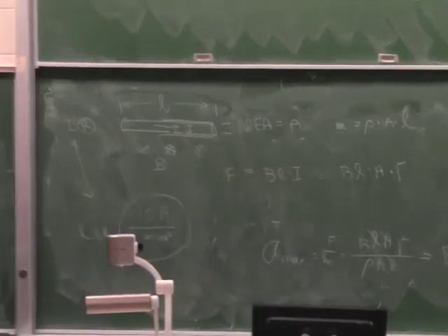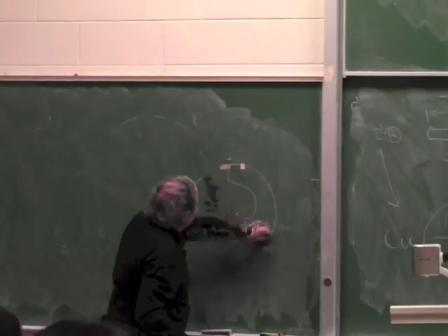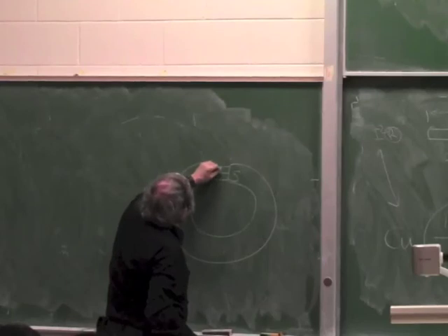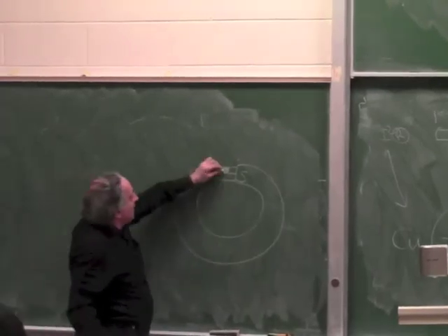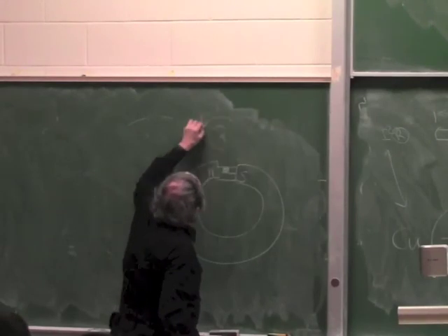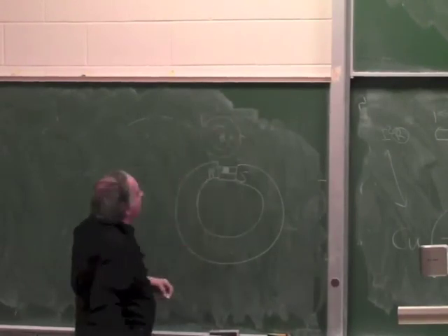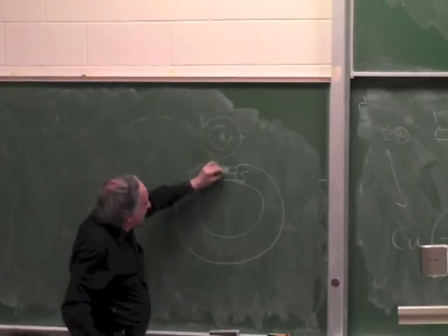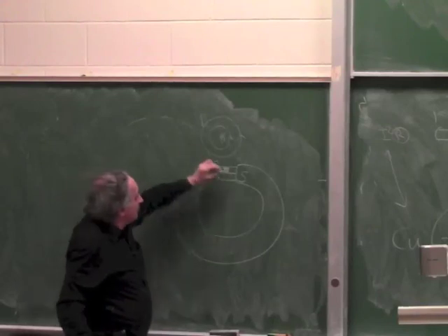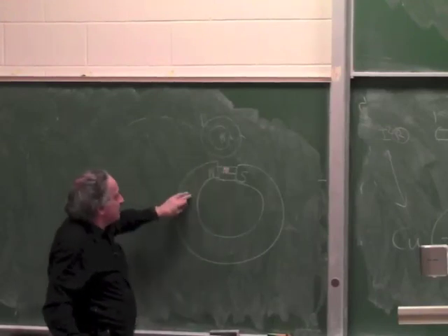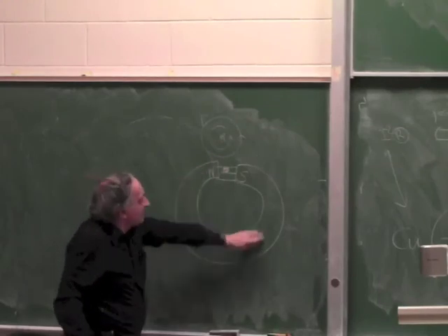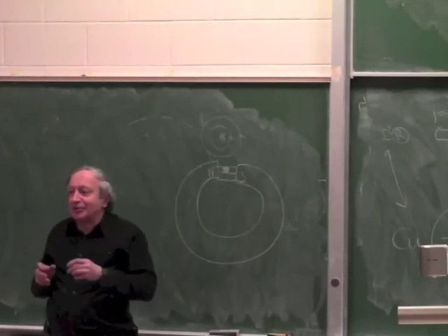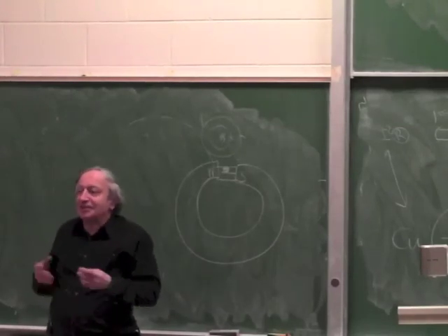Okay, so if I draw it, if I have a permanent magnet, let's draw it like the old-fashioned way, where I have a big permanent magnet, N and S, and I have a magnetic field, and I put a wire inside. Now this wire creates its own magnetic field, as we discussed many times before, and this magnetic field is like placing another magnet inside this magnet. But if the magnet I put in, which is created by the wire, is much stronger than this magnet, it will reverse magnetize this magnet. Because the way this was made a magnet, it was magnetized by a big coil. But the way it was magnetized, it can demagnetize.